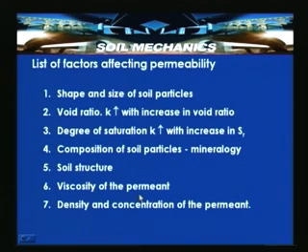And we also discussed that, based on Taylor's equation, k is proportional to d e square, which indicates that with an increase in grain size, an increase in the permeability value can be seen. That is, if d e is the effective particle size, a large effective particle size can have a larger permeability. So, that is the effect of grain size, one of the factors affecting permeability.